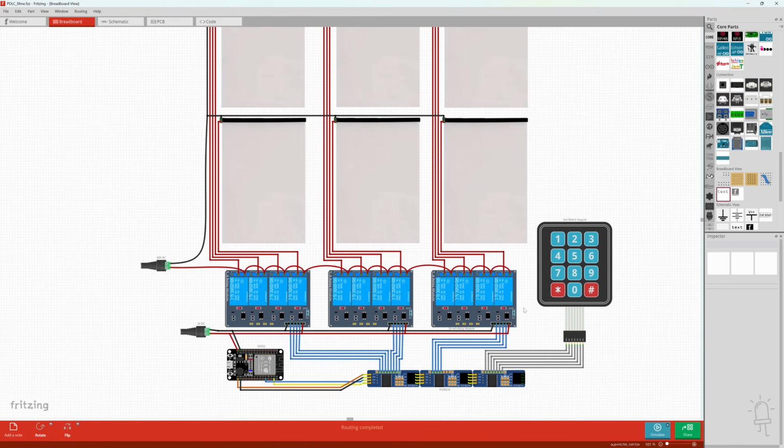Now I should mention that 60 volts is a higher voltage than most projects I make on this channel, which are more commonly low voltage 5, 12 or 25 volt DC. And that does mean you need to exercise more caution to ensure that it is safe. Now current limited high voltage in itself is not dangerous. Static electricity is a good example, which can be measured in kilovolts but has very little current.